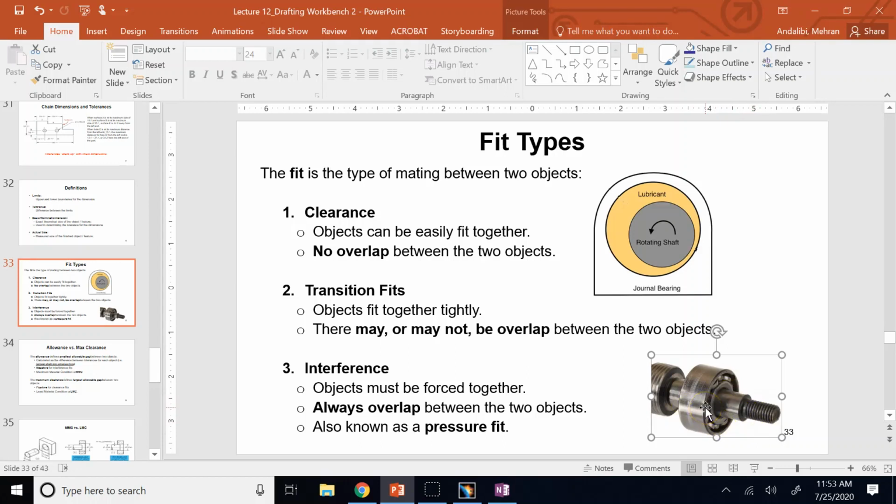And when the temperatures go back to normal, then the materials press against each other, and there is a ton of friction which does not allow one to easily move inside the other. Okay, so that's called the press or interference fit, and you cannot easily separate them, as I said.